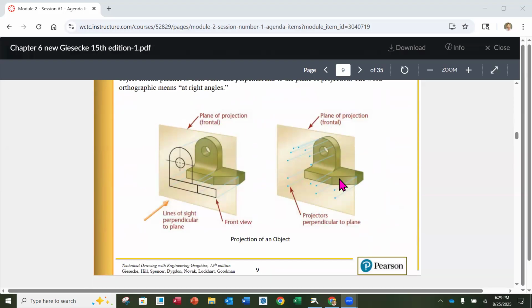Projections, we already talked about this. A projection is really projecting to a surface, and that surface is our piece of paper that we're going to draw on. We're drawing what we would see when we look at that view. So if it's a front view straight onto the part, we're basically going to project all of the points forward to your paper so that we can draw what that view is going to look like. Do you kind of see that? So again, it's like taking that part and showing it. What do I see when I'm standing right in front of it, on the right side of it, top of it, bottom, whatever it might be.